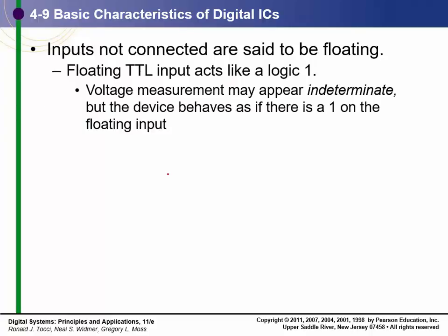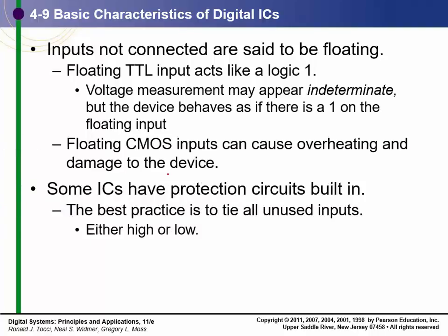If you measure it with a voltmeter or a logic probe, it usually doesn't say, but usually if you leave an input floating, it's going to look like it's a high. It's going to appear that there's a 1 there. Floating CMOS can cause overheating and damage to the device. That's it.